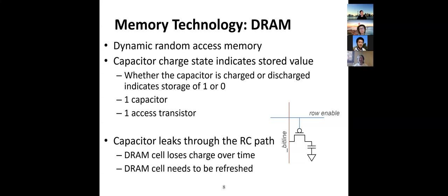In fact, I did some experiments in grad school: if you reduce the default parameters of refreshing the memory, recharging it, it can actually retain most of the values for as long as a few seconds, right? So it's not complete science fiction. That's what I'm trying to say. But usually to have reliable operation, the refresh interval is around 64 milliseconds.